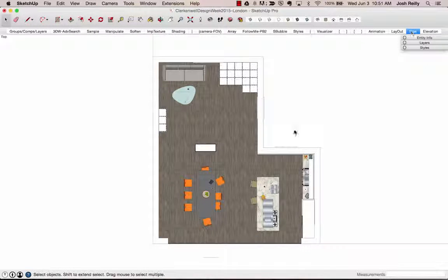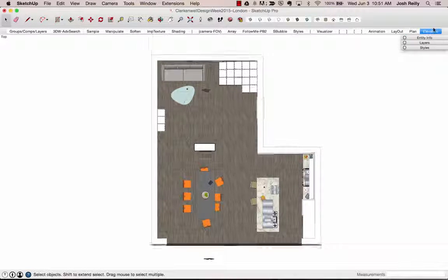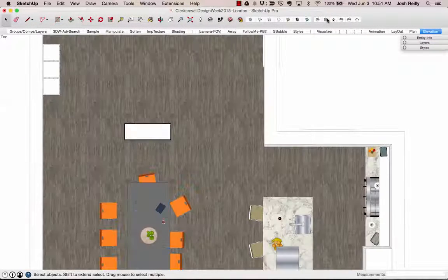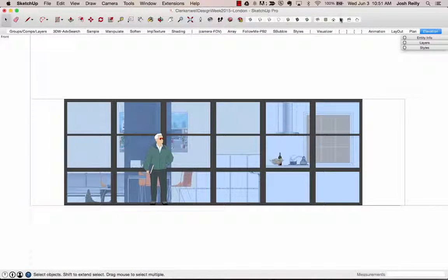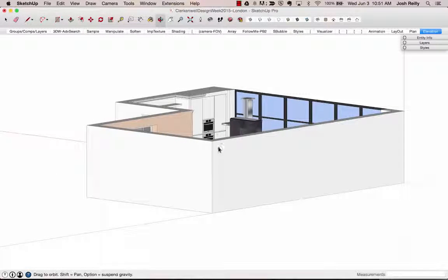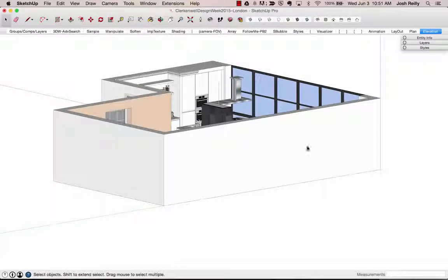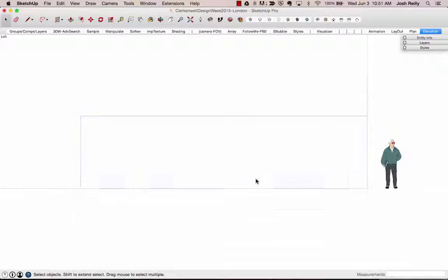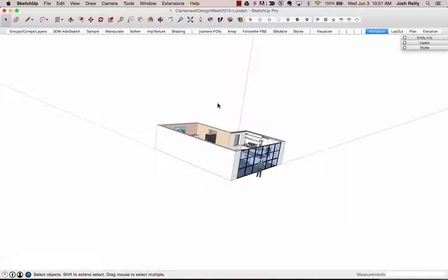In this case, I wanted this scene to just have the perspective turned off for my straight down plan view. And there's elevation. If you have different elevations, of course, you can change with these buttons up here. You can quickly snap to those views. This is not a very complex model, so there's not a lot of interesting things going on there. But if I had an off angle elevation, you can also right click on a surface and choose Align View, and that aligns you to the perpendicular view of that surface. But I want to show you how to go into Layout from SketchUp here.